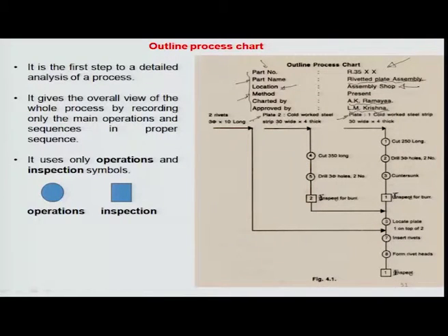And these sheets have some specific dimensions, and the idea is that we want to do a rivet assembly over these two sheets. So, take both the sheets, lap one on top of the other, and then use a drilling mechanism to drill for insertion of a rivet and then form the rivet head, so that you have a proper lock between these two sheets in terms of a rivet. So, this is the whole operation.